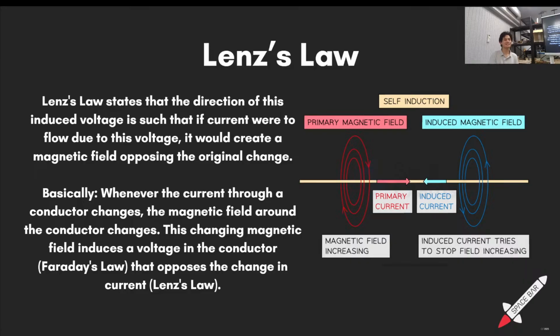Okay, so does everyone accept this? So basically, if you change it, there's some pushback. Yes, correct. So whenever we change the current through a wire, this will, because of magnetism, cause a reverse voltage, which reduces the change in current a little bit. And the reverse voltage can be very high also. It can damage your transistors. Never mind. Yes, reverse voltage can be big. Very big, yes.